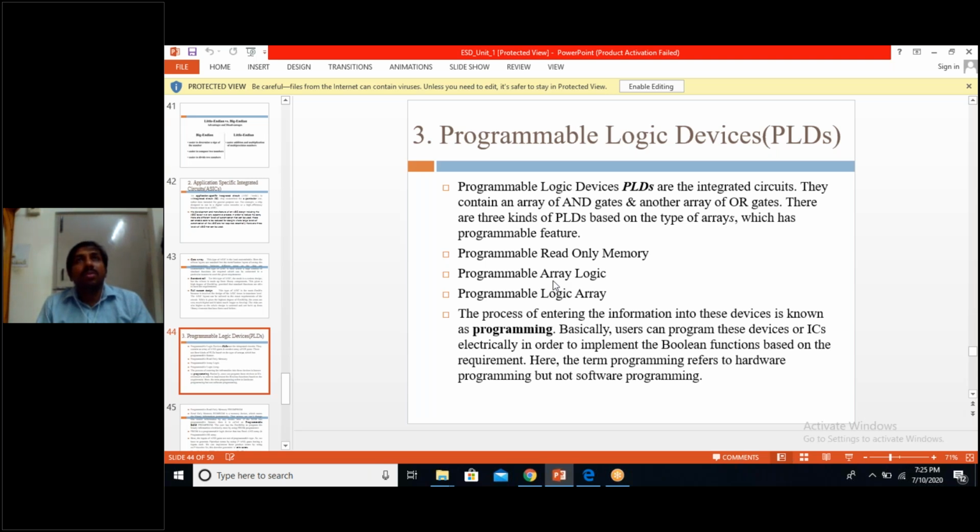So whatever the architecture it is using, read-only memory, if it is based upon transistor switches, based upon the data written in it, some of the transistors will be on, some of the transistors will be off. So the data is written, and no one can alter the data. The only thing is, once your embedded system is switched on, the processor is going to read the contents of the memory, and as per the instructions given by the application software, it will just operate.